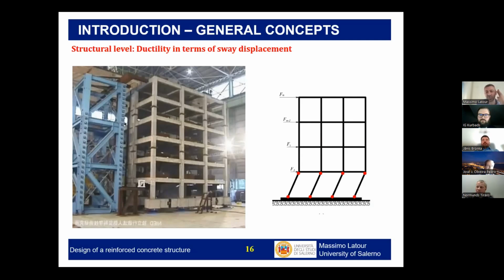Let's say that in this case it was a quite easy decision, because this building is close to the street and the street is at that level, so it's automatically necessary to have this partially under the ground level. If you don't want to do that, you have to use piles or, as you say, a foundation slab, but maybe piles, at least short piles to reach a better soil.